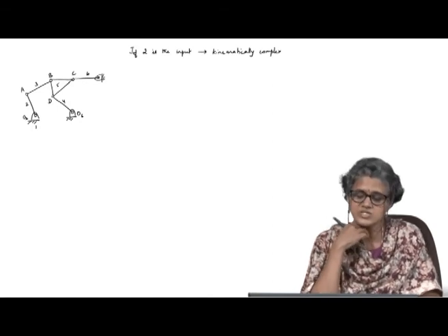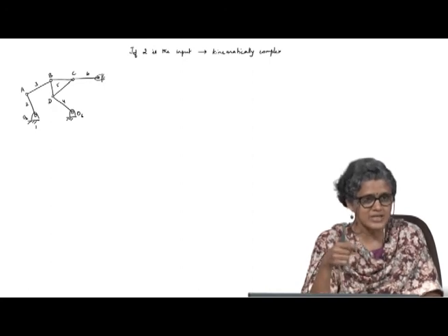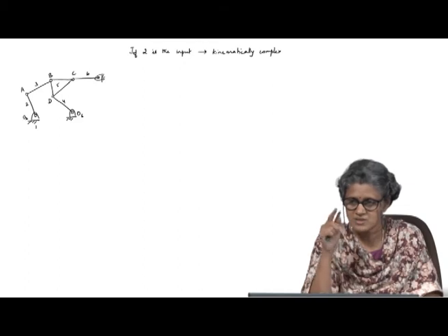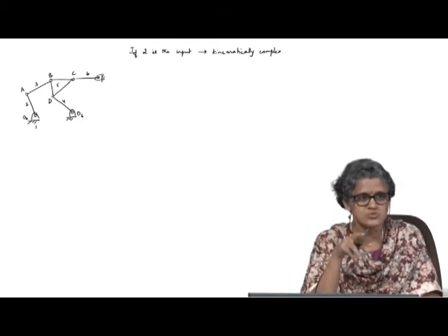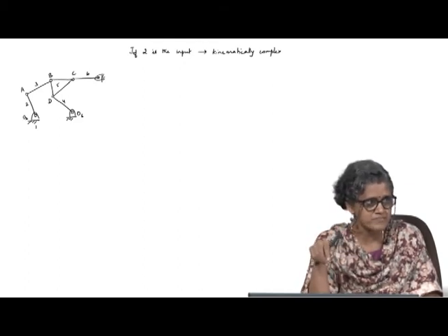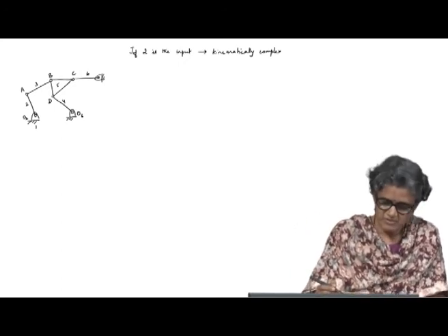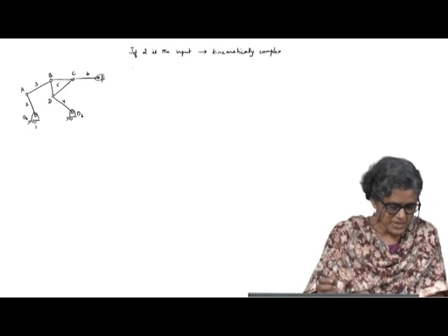You can't scale it directly like you do for the velocities, because you saw that every point has 2 components of acceleration. So, it is not as straightforward as the velocity analysis, just inverting the mechanism.